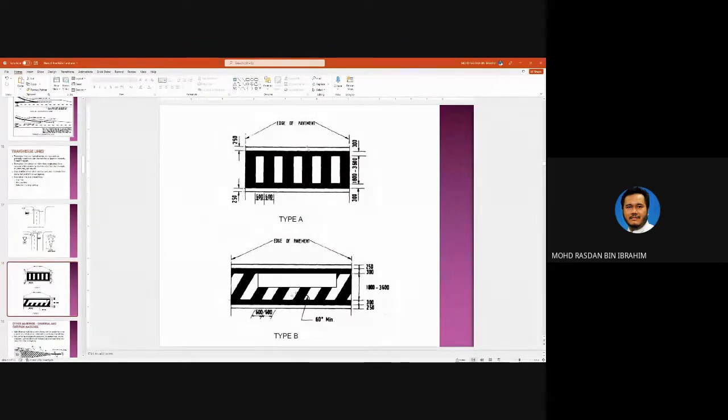So you have the white one here, this is the edge of the pavement, this is the line, and this is the pavement markings. Typically, it is white for pedestrian crossing, but it also can be yellow. Yellow ones normally are used for pedestrian crossings that are signalized, where you can push the button and the light will change to red, so then you can cross.